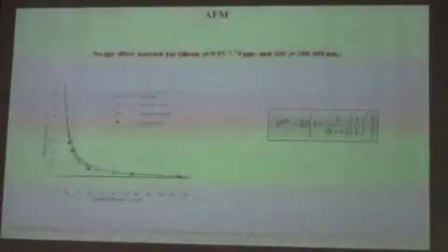And we can compare it to the chosen coupled stress bending rigidity, where there's only one material length scale parameter. And by doing so, for the materials, I tested silicon in a range of maybe 1 to 8 micrometers, and for silicon nitride in the range of 200 to 800 nanometers in beam thickness. I detected no size effects in this range.